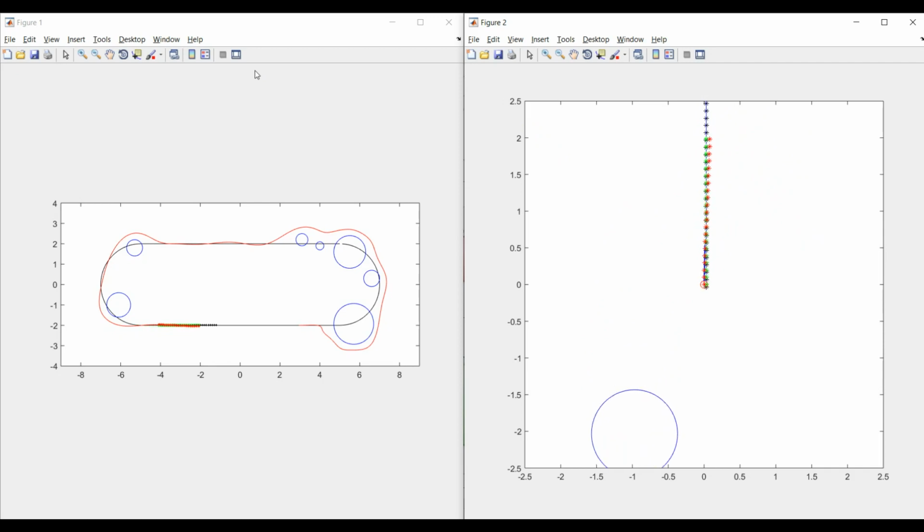And this is actually done to ensure that the problem stays feasible, first of all, since we have introduced some slack variables that will help against the feasibility bit. We also want to ensure that small uncertainties will not cause the robot to drive into the obstacles. We want it to keep a safe distance to the obstacles itself.